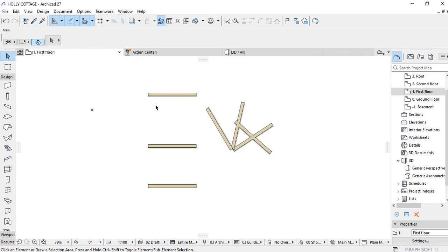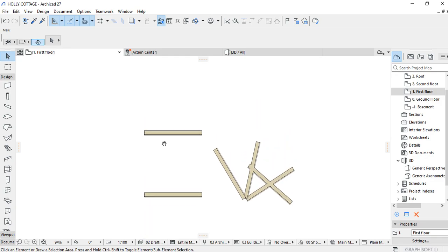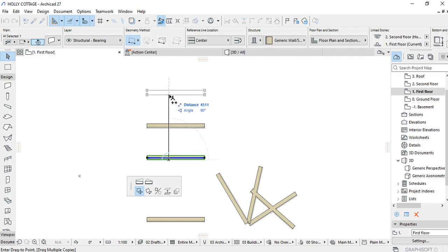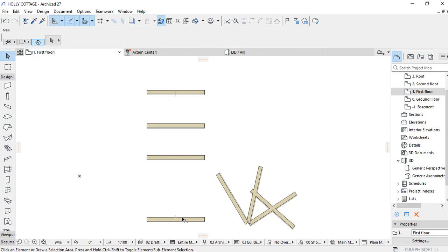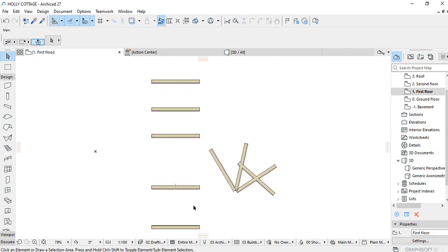So the other icon is drag, of which we've already seen how to drag to create multiple copies. So you select it, right click, drag, Control Alt, then you can create the multiple copies as you've seen before. So for the mirror tool, you're able to mirror it once. You cannot create multiple mirror axes.